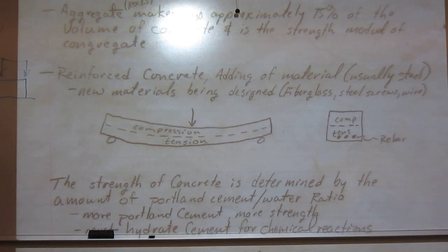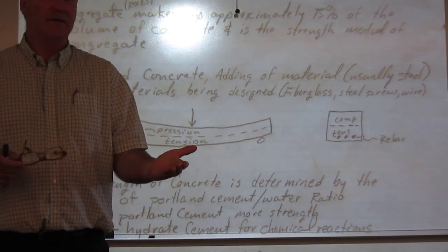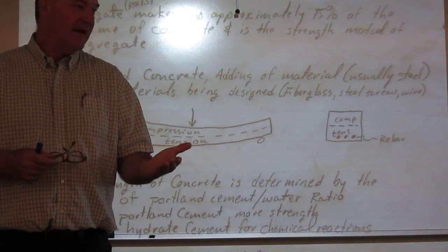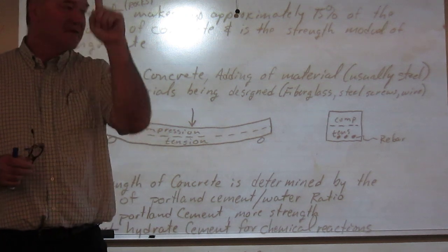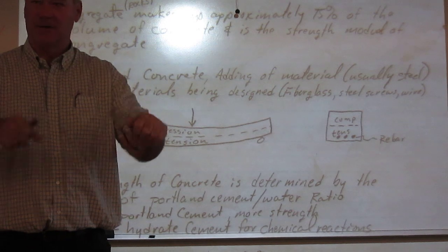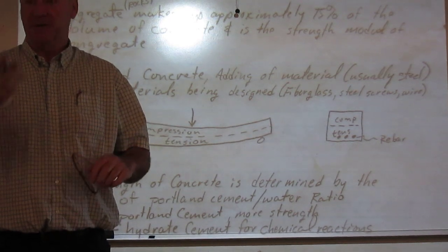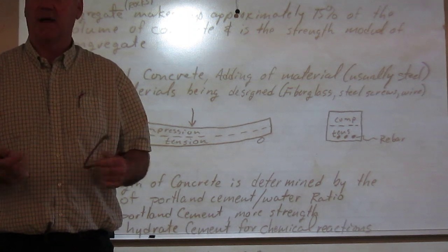The problem you get with it when you finish a slab, like we're walking on a concrete slab right here, right? And you're out in the hallway. You see how smooth it is? If that has fiberglass in it, those little strands are sticking up in there and it's hard to finish the floor. You have to use basically one of those walk-behind buffer type concrete machines. And then they'll shear that stuff off and you can't do it by hand.